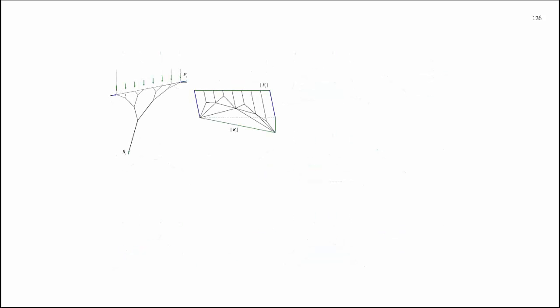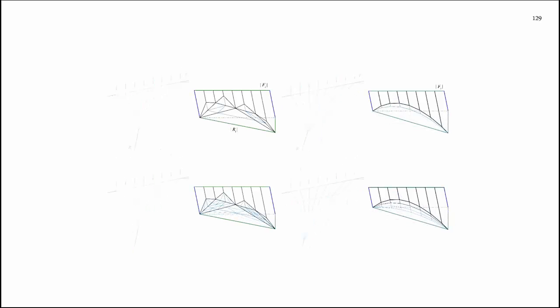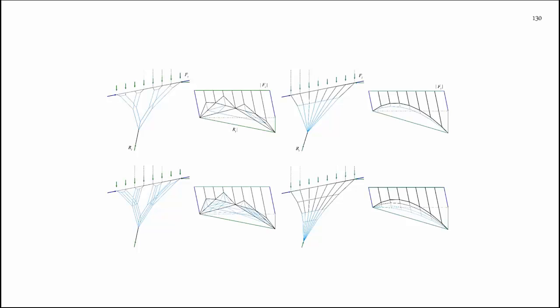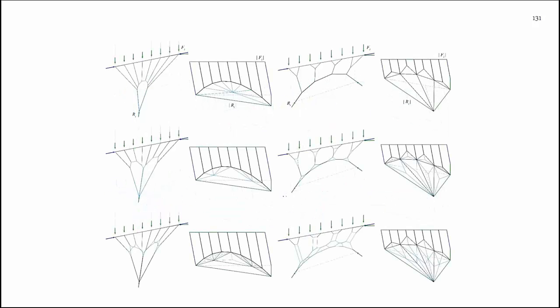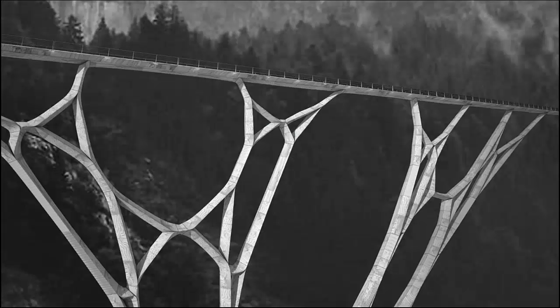Okay? So, for instance, in this case, if you have a branching system, you can manipulate or just subdivide the force diagram of the branching, and you get different types of branching structure. You can see that in all the examples that I'm showing, the force diagram doesn't change that much. The only thing that I'm changing is the level of subdivision and combining different methods of subdivision to get different forms. So you can also combine arches and branching systems and get really interesting structural systems that are all compression-only, and they're all in equilibrium according to the force diagram. Then later you can translate, of course, each scheme into the architectural language, to start with a concept that originally has some structural meaning, and then work from that point, right?